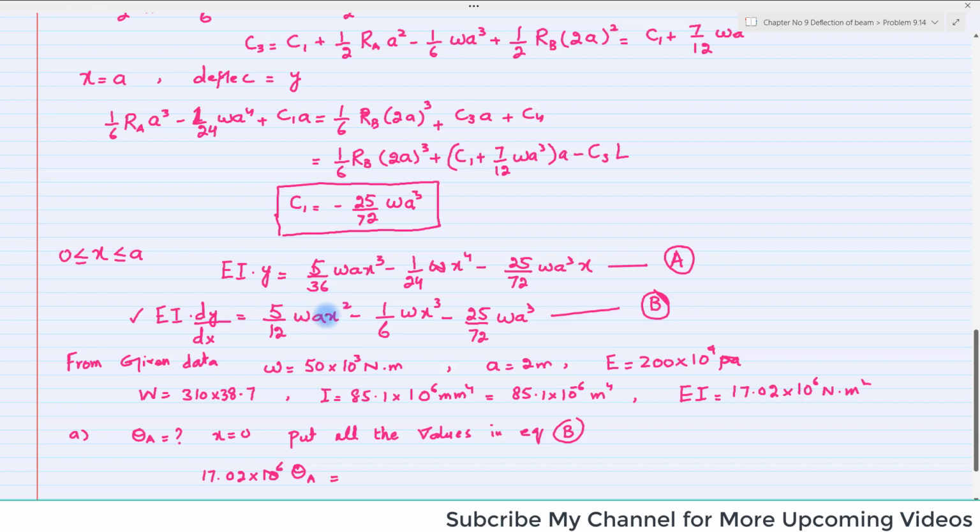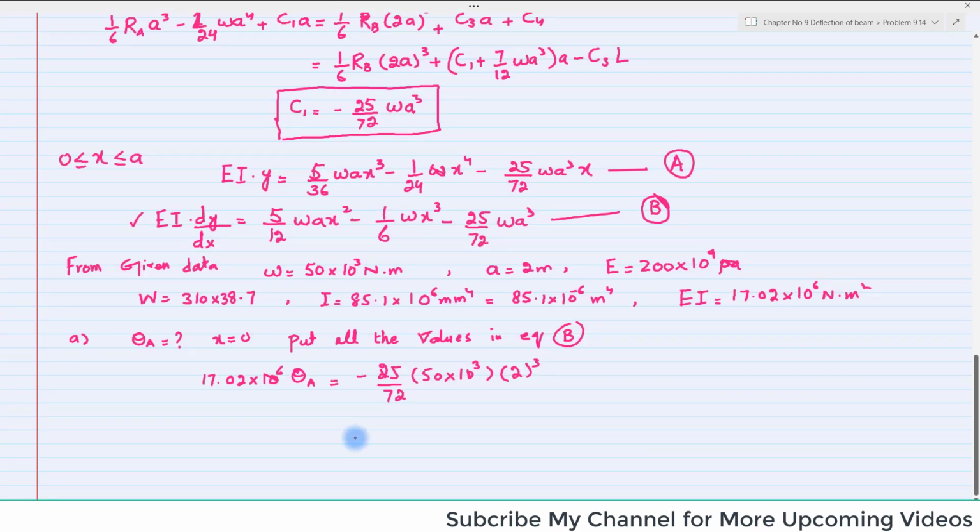At x equal to 0, this term will be 0, this term will be 0, and we will only have minus 25 over 72 W A cubed. W is 50 into 10 raised to power 3, and A is 2, so 2 cubed. When you solve it, you will get the slope at point A equal to minus 8.16 into 10 raised to power minus 3 radian. Clear? It means theta is clockwise.